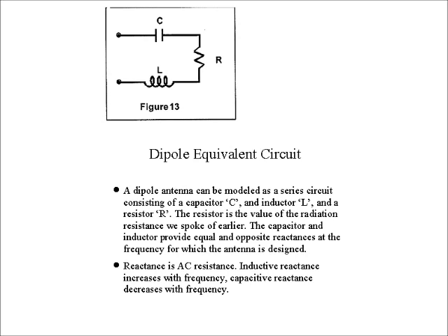And believe it or not, we have one of these. I want you to see, how long would a 40-meter antenna be? 66 feet, or about 20 meters. That's my 40-meter antenna. What's here is a small inductor.